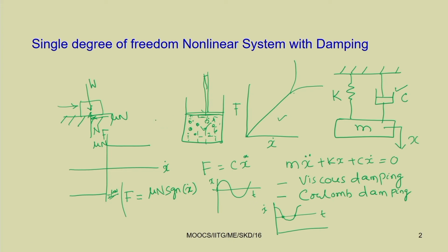Here, particularly, you see this MRF, magnetorheological fluid. By using this magnetorheological fluid type of thing, we can make this damper active, otherwise with a simple fluid it can be a passive damper. Now, you know about the passive damper and the active damper also. In the case of an active damper, we can change the damping property by applying some external stimulation. For example, in this case we have applied the magnetic field, and by applying this magnetic field we have changed the damping property.